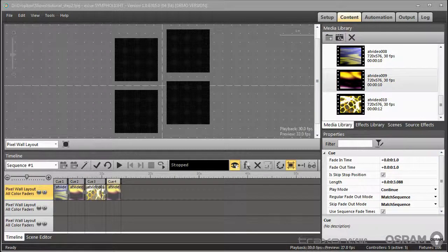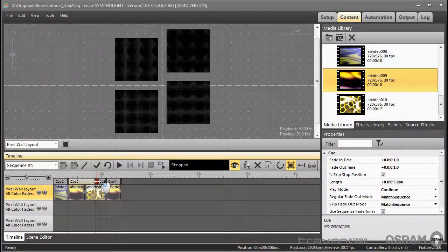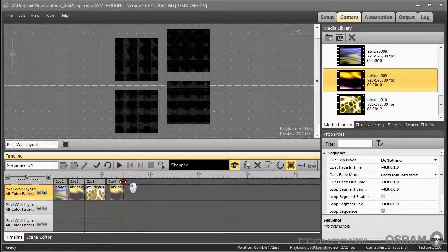There's another little trick that is not obvious. If you keep the control key pressed while changing a cue, you can here see that the remaining cue is also resized. If I use no key at all, nothing else changes, and I can use the Alt key and also the content will move. And I can combine the Control and the Alt key to adjust my sizing.